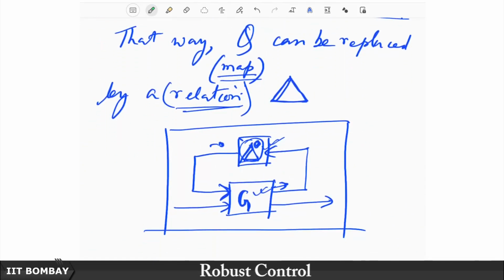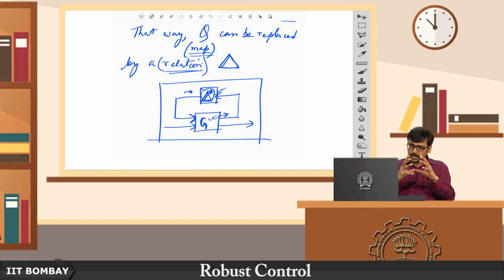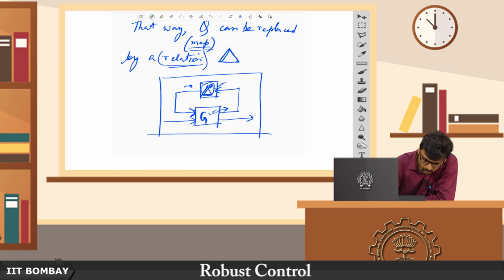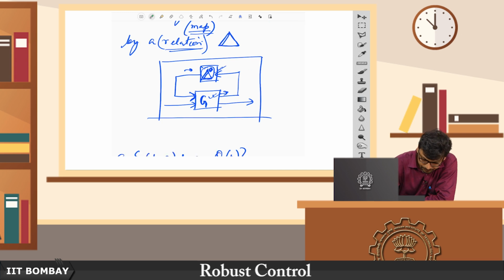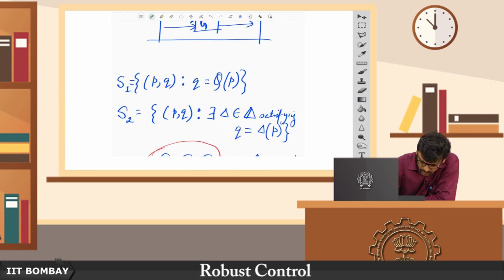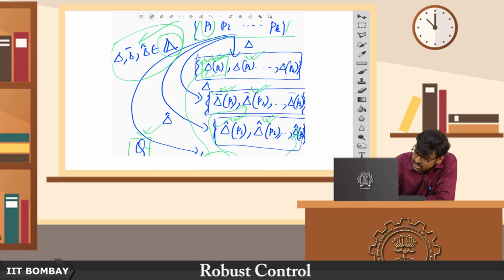At the heart of it, we try to get the essence of a simplified linearized dynamics of a system and a set valued mapping, a set of linear maps, which are an adequate replacement for the more complicated potentially nonlinear map. Then we try to address this overall system where this G and delta capture the behavior of GQ adequately.